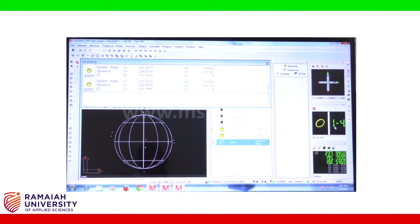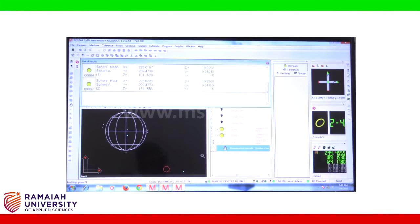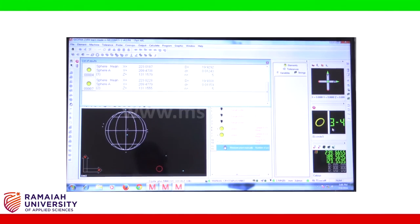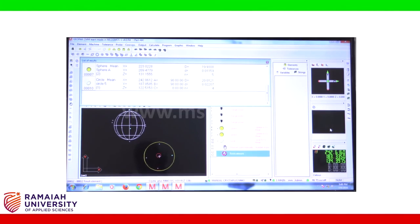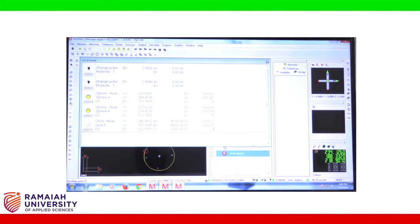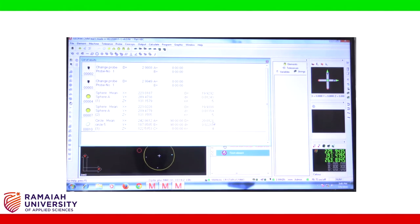So let us get the first coordinate point. The first coordinate point is obtained, second coordinate point is obtained, and the third is obtained, the fourth coordinate point is obtained. Now the circle diameter you can see here as 20.0121 mm. So this completes the measurement of the circle diameter.